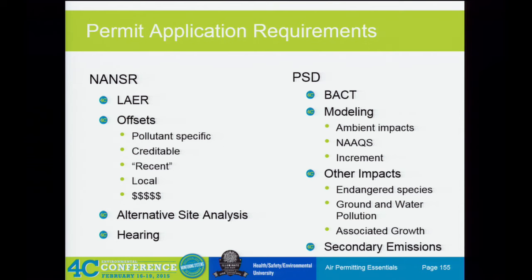You can be above this concentration for ozone, you cannot be above this concentration for NOx, right? So while you're in a non-attainment area for ozone, that area is in attainment for NOx. So you're in non-attainment area for ozone, PSD area for NOx. So a project can be non-attainment and PSD for NOx. But there is no NAAQS for VOC. So it's going to be one or the other.